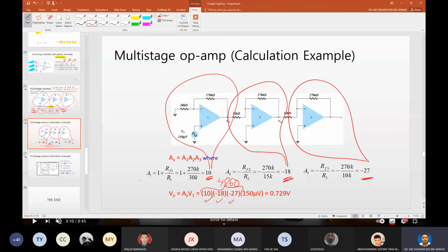You can imagine the sensor signal is very weak. When the sensor detects your pulse, the difference voltage is very small, maybe in microvolts. Your electronics normally work in 0 to 5 volt, so you have to amplify it to 5 volt. You need an op-amp to amplify it so that it can be usable in your circuitry.